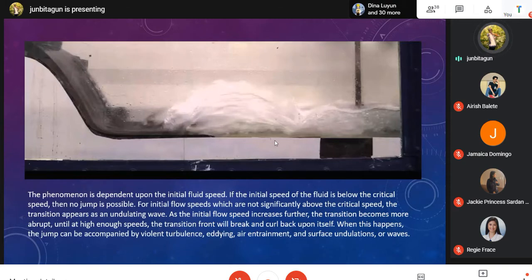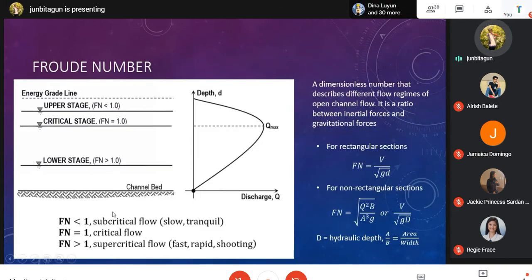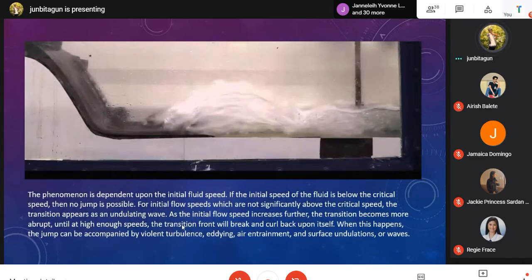Right? Regarding the Froude number, let's go back. So when your flow is subcritical, or slow, and then you suddenly block it to apply a hydraulic jump, that can't happen. It only happens with supercritical flows. Okay? Then you abruptly transition it to slow, to equate the energies, so the potential energy is what changes. So this is the explanation.